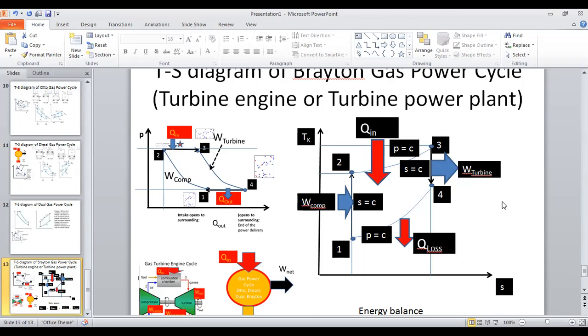Instead of expanding, this is for compression, and of course this leads for suction as well. So receiving intake, compress it, pass to combustion, and then expand that energized gas through the turbine. So all the components are open flow systems. We have learned about this.